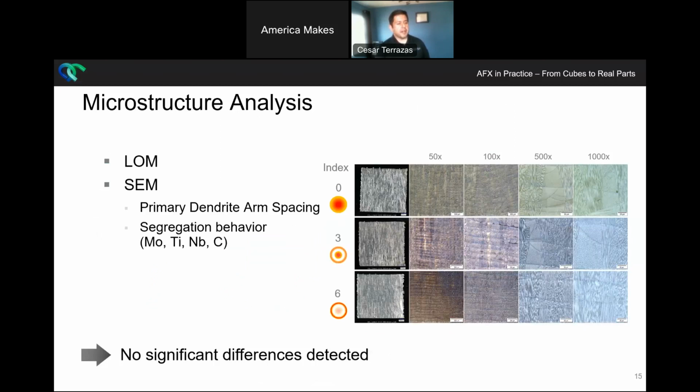So the very first thing that they tried was basically your regular microstructural analysis, doing an optical microscopy assessment, as you can see in these micrographs, depending on the emission mode. And then you can see different magnifications for the micrographs obtained for the material. And in here, there's not much difference when it comes to the melt pool dimensions and melt pool characteristics, right? Very similar, although as you will see later on, the melt pools that are generated by emission mode 3 and 6 are shallower and smaller, like flatter, compared to the regular melt pool that you see normally in these processes.